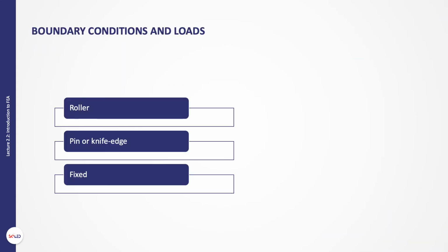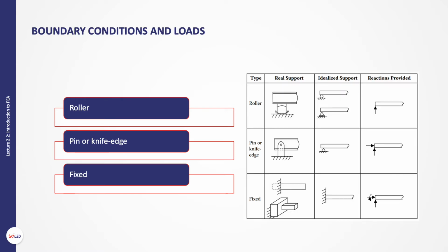Boundary conditions are related to the connection of the body to the environment, and usually refer to the restriction of displacement of a part of the body. Thus, in the event of a fixed, hinged, roller or contact, we appropriately restrict the movement of the node in the position of the link. The loads in a mechanical problem can be concentrated forces, distributed forces and pressures. The concentrated forces are imposed on the nodes, the distributed on the lines and the pressures on surfaces. In addition to forces and pressures, we can also have loads throughout the body, such as temperature change and gravity.